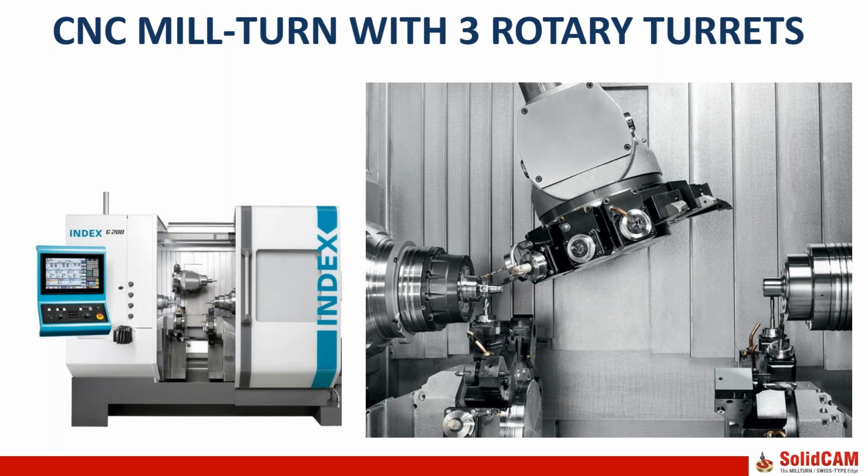This is a machine with rotary turrets. Actually, this machine has 3 in a different configuration again. And again, it looks complicated. And also notice there are 2 spindles, main spindle, and this is what we call back spindle. It's easy to remember, back spindle, right? This is where the tailstock used to be. And 1, 2, 3 rotary turrets. That is something which you don't see on this picture too well, but on the left picture you can see it. There is also, on the other side of the rotary turret, a spindle turret, but we will see it later.